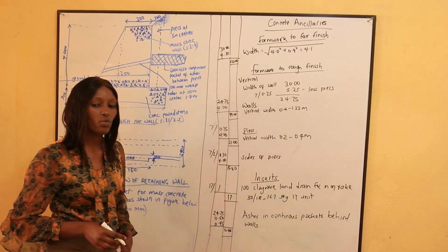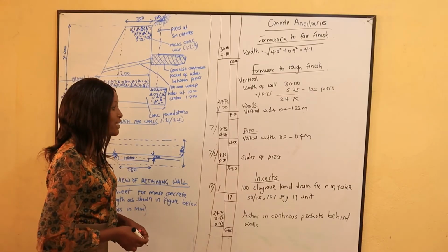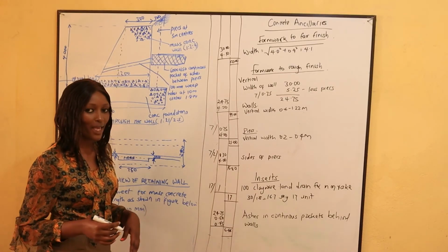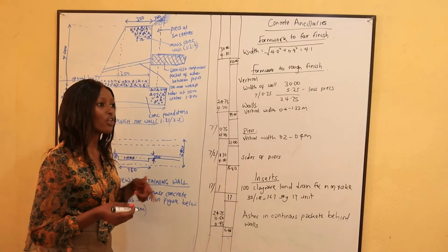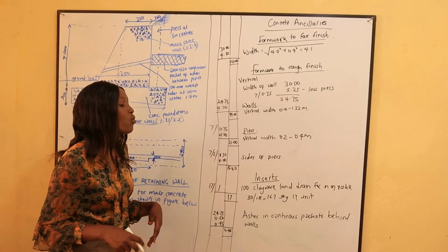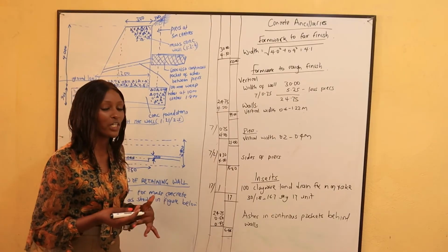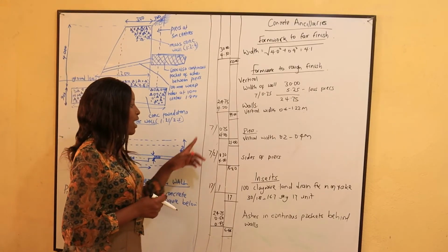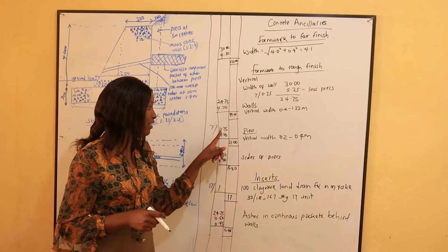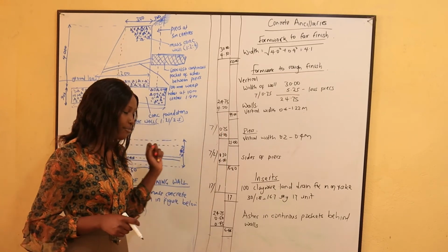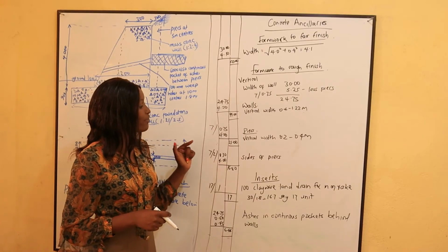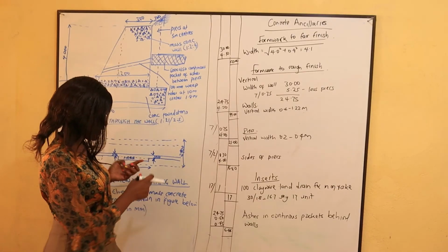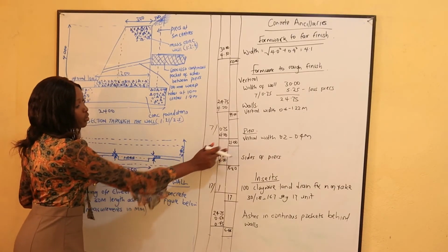Alright, now let's go to the formwork for the piers, the one that shall be holding the piers, because first of all we shall do concreting in the piers. So first we shall do formwork for the piers. So what area of formwork shall be required for the piers? We have 7 piers. The length of each pier is 0.75 meters and the height of one pier is 4 meters. So the total area for the piers on the length side, which is here, shall be 21.